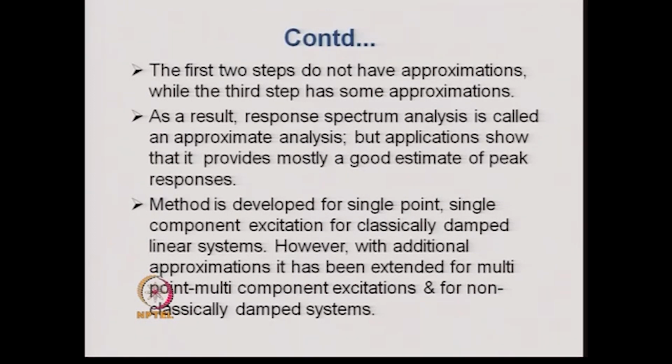So, first we will look into how we develop the required equations for obtaining the response using the response spectrums of earthquake for single point, single component excitations and for classically damped linear systems, that is where the damping of the structure is constructed out of the modal damping ratio, and it is defined for one type of material.